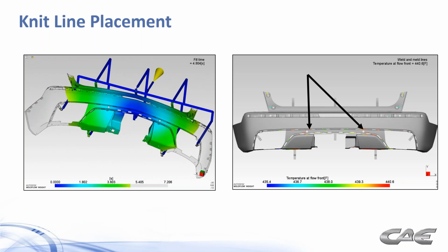We can say, okay, when the flow front of this filling pattern gets back to this certain nozzle, go ahead and fire that nozzle. So maybe we want to backfill the runners, or maybe we want to trigger it at some other location for some reason. So the mold flow output is going to tell you the time at which each one of those nozzles fires, even though our criteria was to allow the flow to get back to the nozzle.